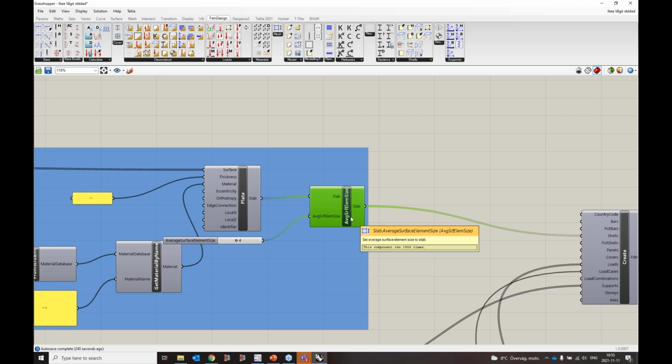You could make sure that you save the results, you don't have to save all of the results, but some of the results that you want to use for your mesh consistency check. And you could save those to Excel files or somewhere, I don't know where you want to put them. But then you could try all the different versions and have some kind of criteria for when you think that the mesh size, well, the results converge.